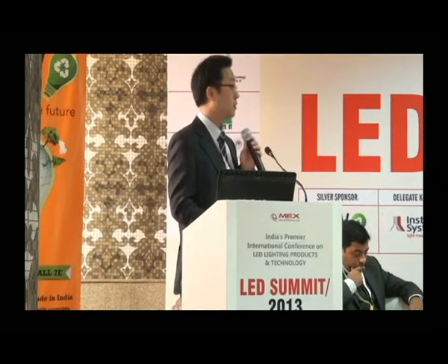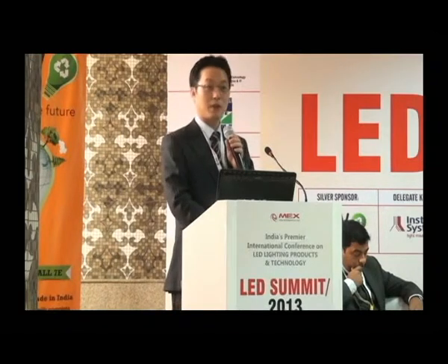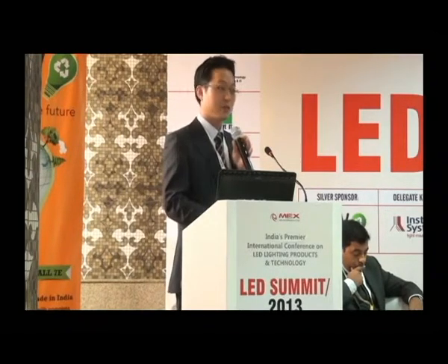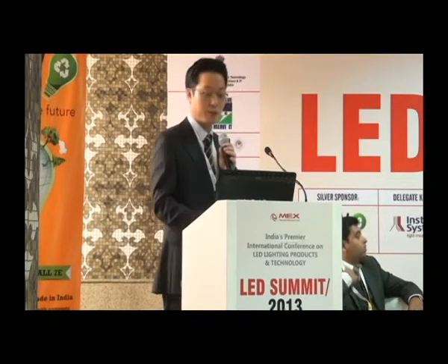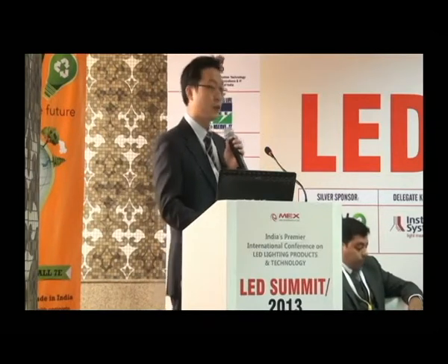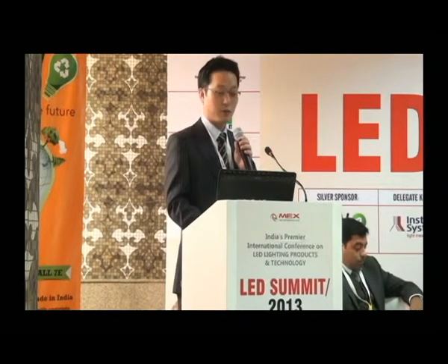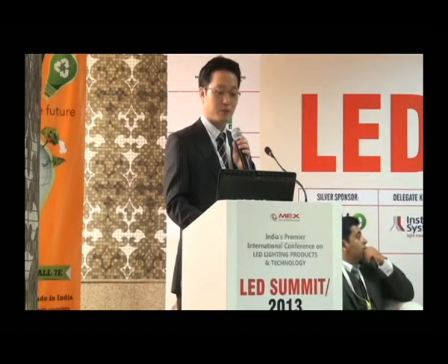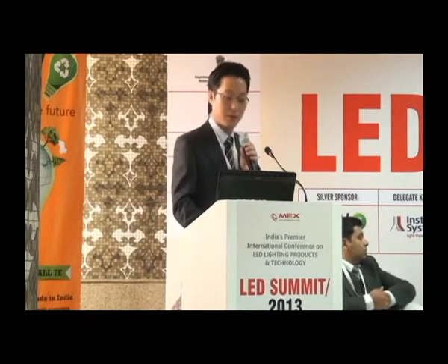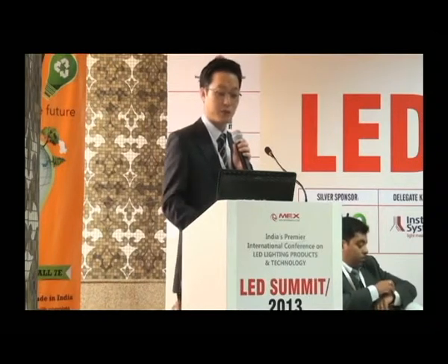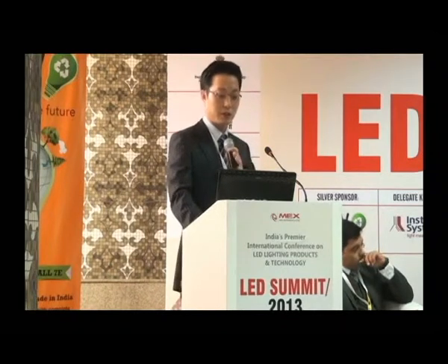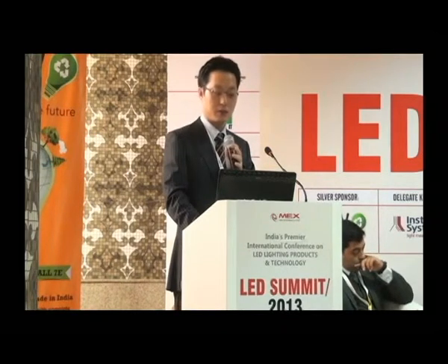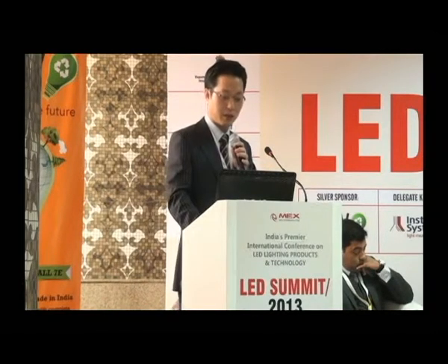I think the LED industry is very similar to the semiconductor industry. In the semiconductor industry, if some material shrinks or makes some byproducts, it is directly related to defects. The main stress of the LED customer is, as I mentioned before, decreasing the defect ratio as much as possible. That is the reason why addition-type hydrosilylation silicone is selected for LED application.